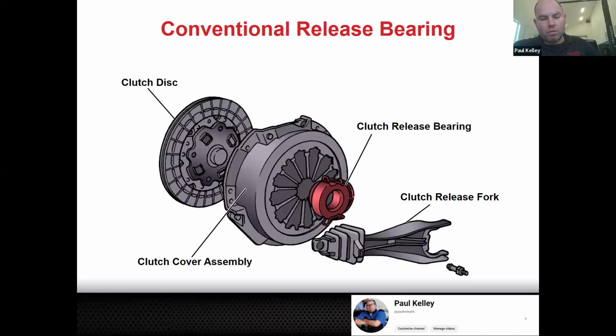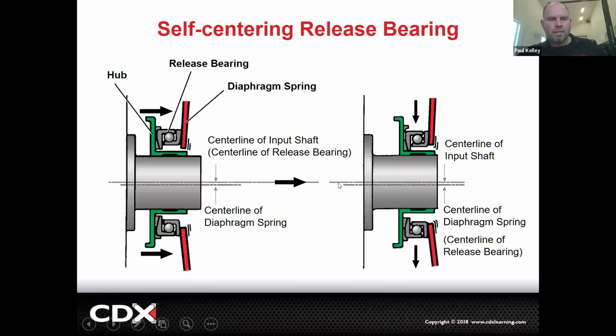So that's why it's critical when we do the clutch job, make sure you're cleaning all the clutch dust and you're greasing all the right points with the right type of grease, which is a high temperature. It's really darn similar to disc brake lube. Okay. So we'll come back a little bit on the service because we got a photo sequence of how to do the work. Okay. And then this is a different type of bearing.